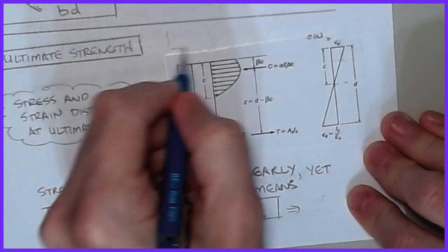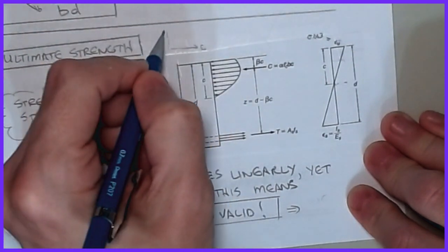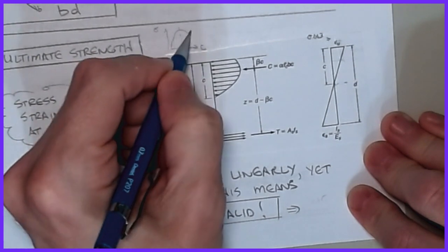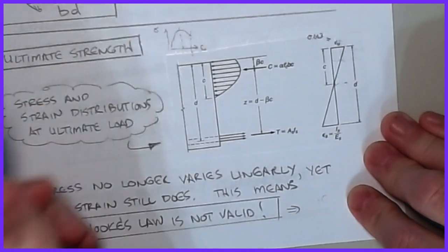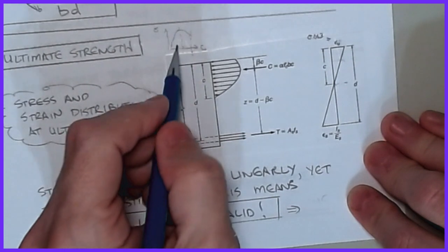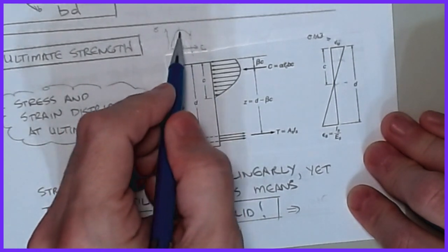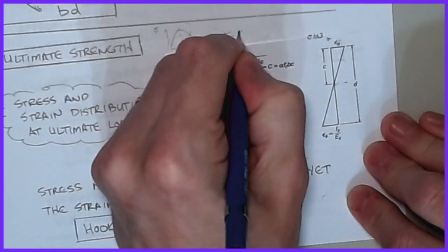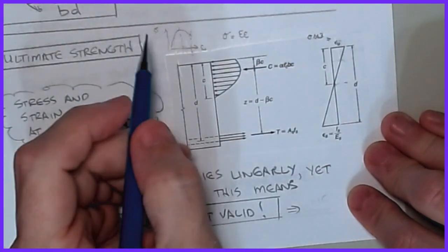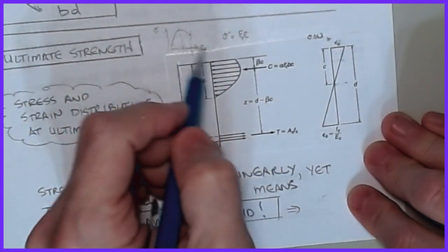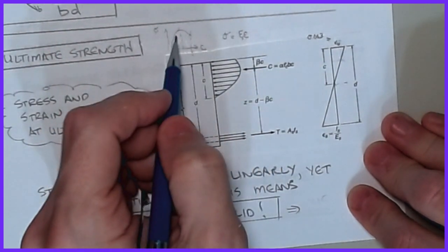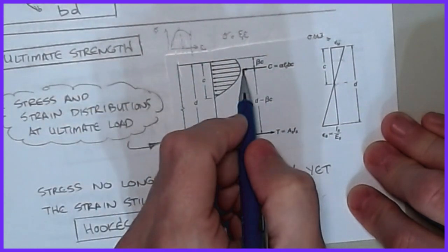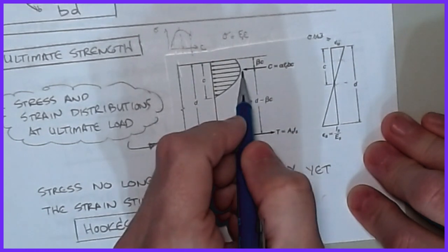Because remember, if I plot strain and stress for concrete, it was a curve that looked something like that, where this was my ultimate and this was my maximum. The relationship between sigma and E no longer follows Hooke's law. It's not the same value, because if E is constant, we violate this. So you look at this picture, it's kind of a mirror image. My peak stress in the concrete beam does not occur where the peak strain is; it occurs somewhere else.